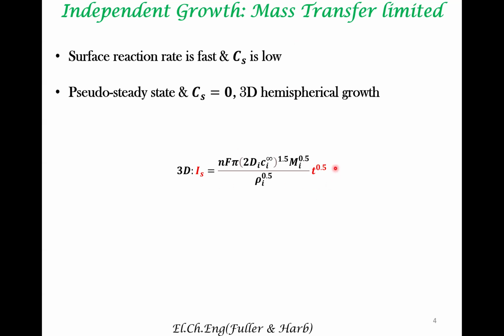So square root of t is an important term that comes when diffusion plays an important role. People who have, let's say, chemical engineers or materials engineers who have looked at mass transfer, you might have looked at ballistic phenomena as well as diffusive phenomena. So here, square root of t dependence gives a clue that diffusion plays an important role.